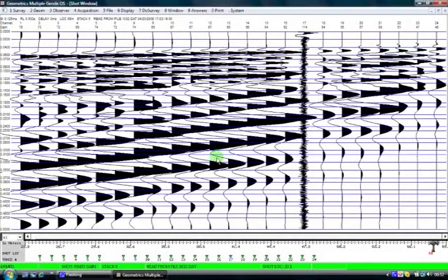This slide is a typical seismic refraction record, which I will now explain. Across the top we get our geophone numbers from 1 across to number 24. The second row, which we'll see later as we make some adjustments, is our trace scaling factor, which is applied to each of the geophone channels.